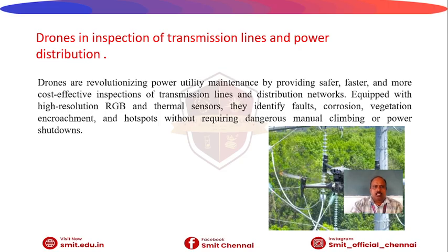So drones, in the case of inspection of transmission lines, are revolutionizing power utility maintenance by providing safer, faster, and more cost-effective inspection of transmission lines and distribution networks. Equipped with high resolution RGB sensors and thermal sensors, they identify faults and whether the transmission lines are in good condition or not.